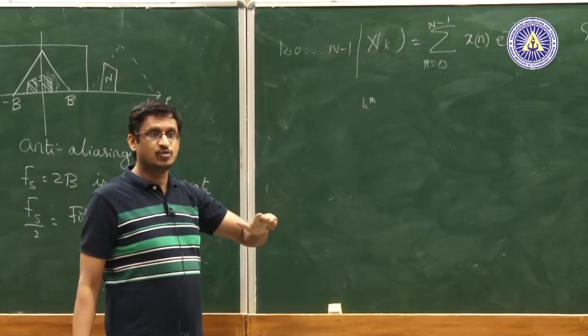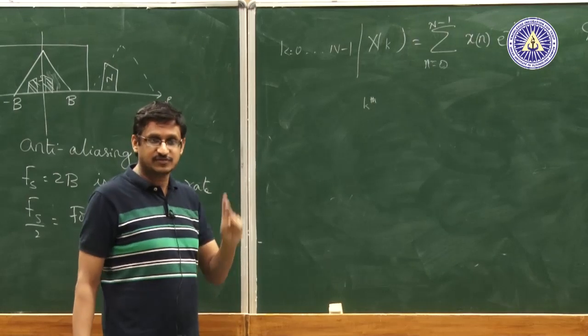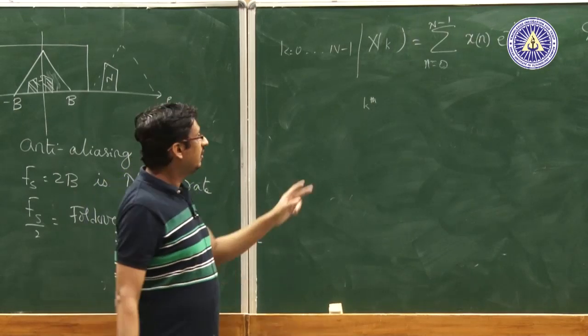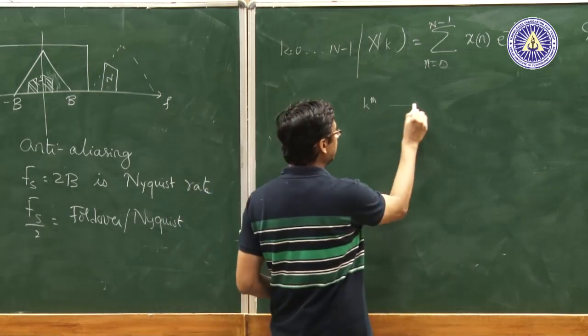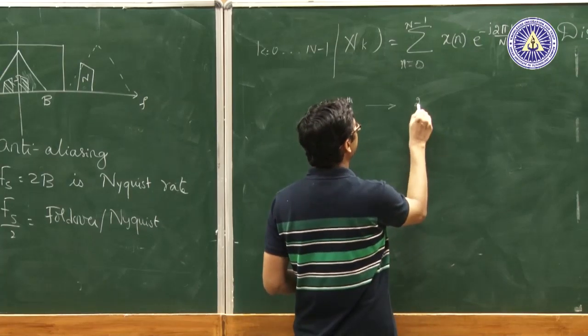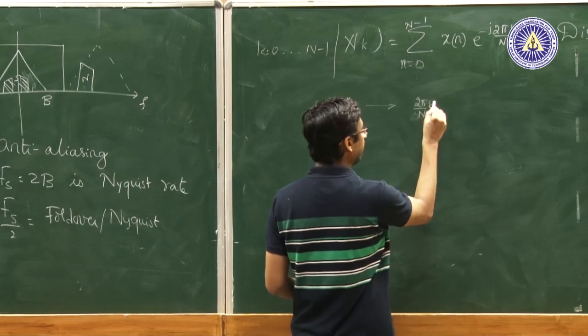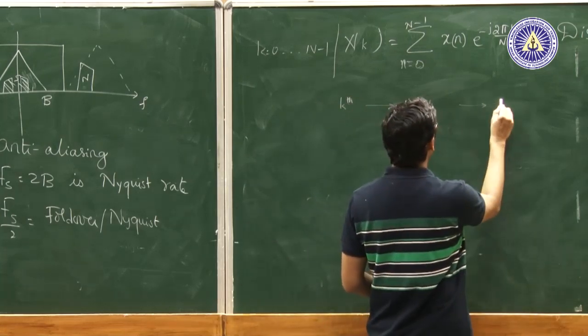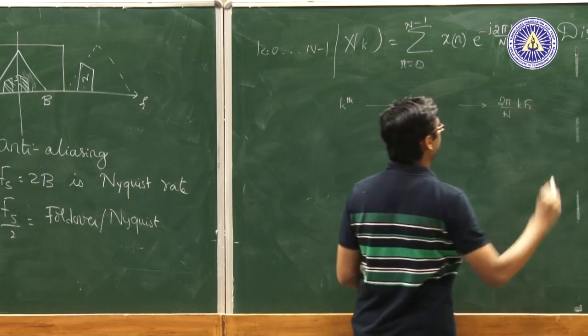So, someone tells you the original sampling rate of the signal and then asks you what are the different frequencies involved, then you can look at each kth term and actually obtain the original analog frequencies. So, the digital frequency corresponding to this k will be 2 pi by n times k, but the analog frequency corresponding to this one will be 2 pi by n k fs.